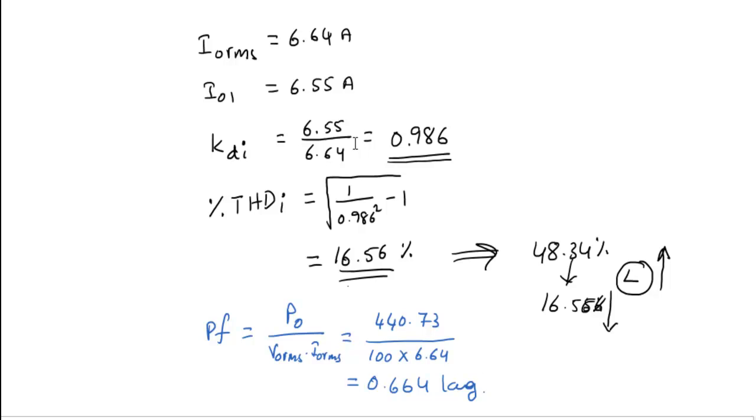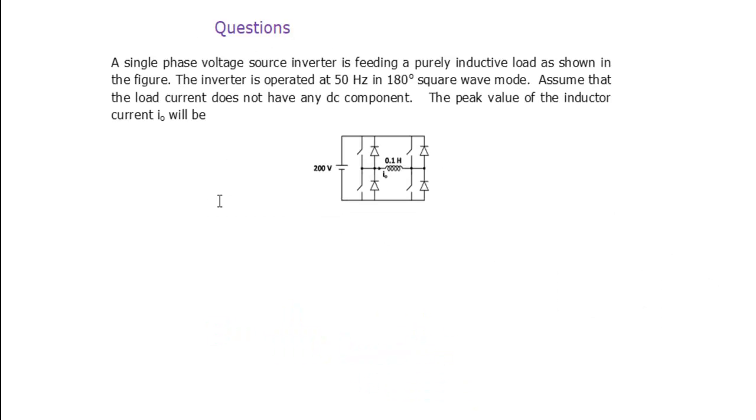Sometimes, if you want to calculate approximate values with a little difference in the decimal point, we can calculate using the third harmonic and fifth harmonic. That's sufficient. No need to go further. That means fundamental component, third harmonic, fifth harmonic. If you get possible time, then go for the seventh harmonic, then we will get the proper values. Then move on to the next question.